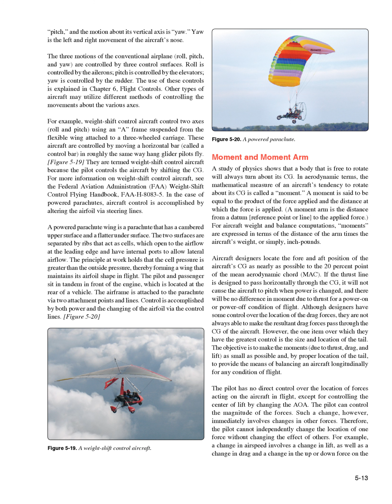The three motions of the conventional airplane, roll, pitch, and yaw, are controlled by three control surfaces. Roll is controlled by the ailerons, pitch is controlled by the elevators, and yaw is controlled by the rudder. The use of these controls is explained in Chapter 6, Flight Controls. Other types of aircraft may utilize different methods of controlling the movements about the various axes.